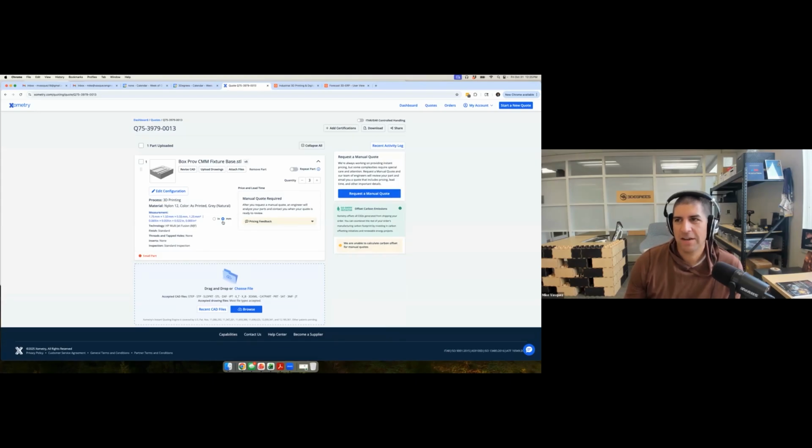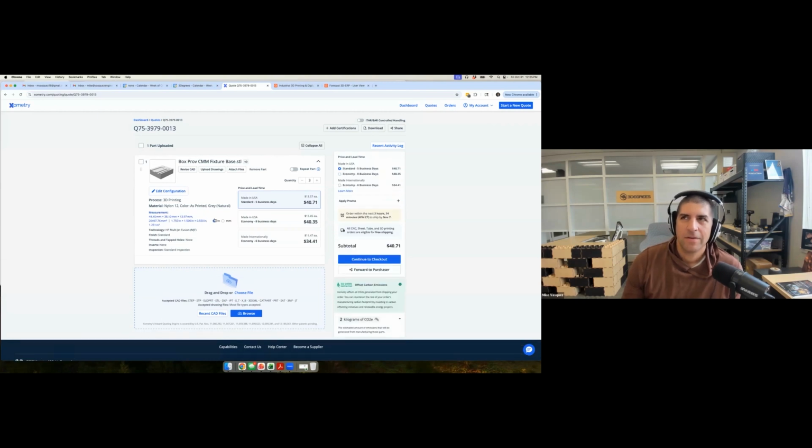In some cases, I've seen you drop your part in and they're unable to quote it, because instead of 1 inch by 2 inches, it looks like 1 foot by 2 feet, and it won't fit into any printer. Then you wonder, hey, what happened there? Sometimes you just want to make sure that your dimensions are right, so have an idea of what you should expect them to be when you're going in.